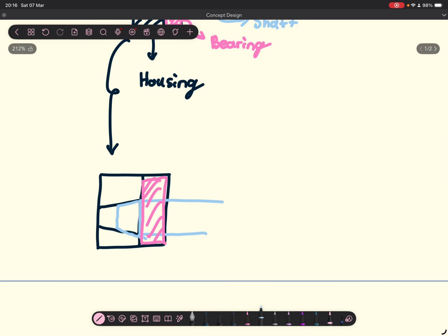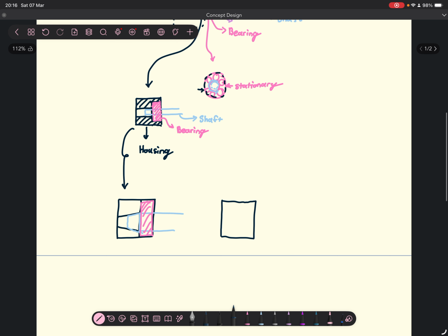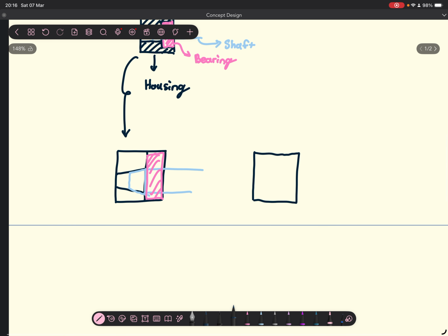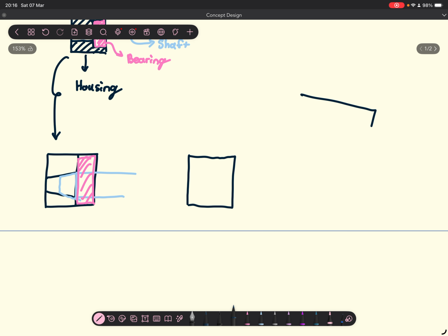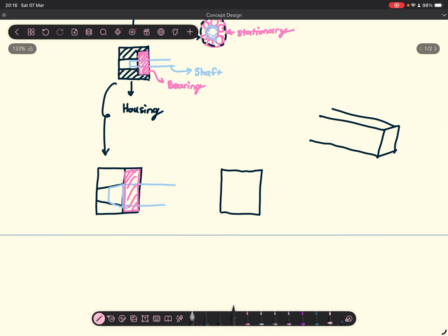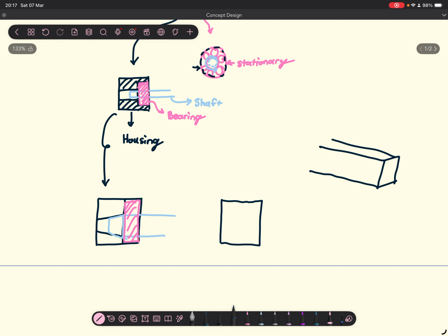And then if you have a second bearing housing, you just need to make sure that the two are aligned on the same spot of the beam itself, right? So maybe on your beam itself, you specify that there must be plates or something, or like, okay, honestly, I don't think you need to think this far, but do consider the alignment of things and try and make it easier.